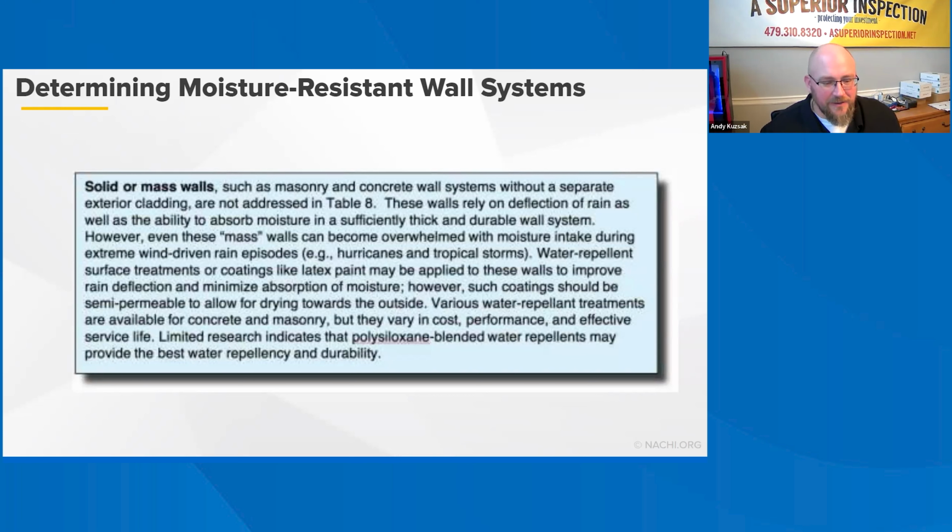Again, if you see a brick veneer that has a kind of sheen to it, that's applied over the brick and over the joints, or if you see a paint, any type of color difference that is different from the brick, pay close attention to the brick face. It should be obvious if it is not the correct application for that situation, in that if it's not permeable, you will often see the face of the brick spalling off the home.